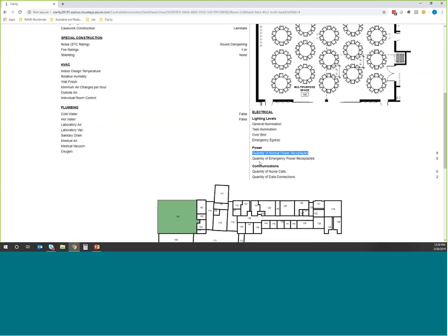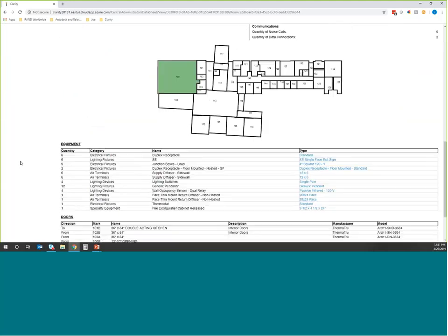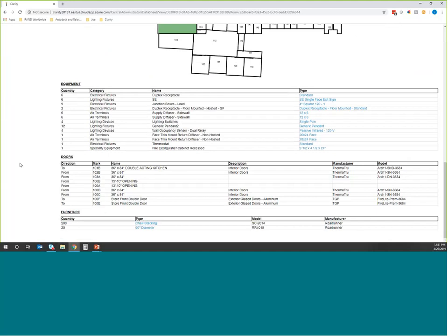So not only are we counting what's happening inside a given Revit file, but we're aggregating information from the collection of Revit files that makes up the project. And we're reading through that link barrier that Revit can't always handle, doesn't handle on its own. We can get past that because now we've aggregated that information inside SQL. So here's that room relative to the other rooms in that level of the building, other furniture, fixture, equipment, things that exist in this building that we need to care about.